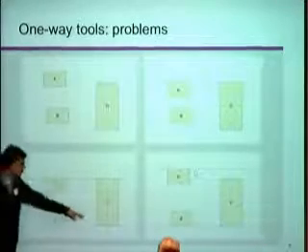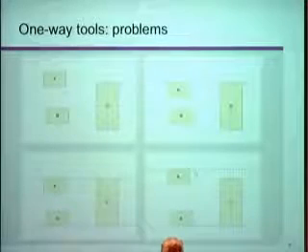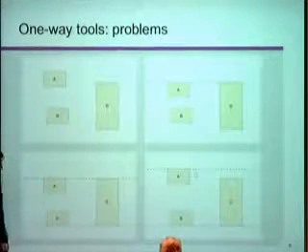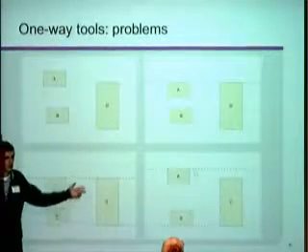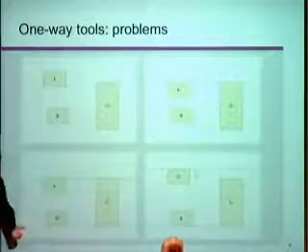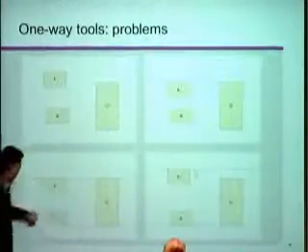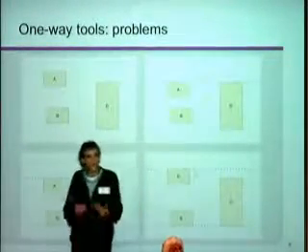Next, they select shape D and they select shape B, and they create an alignment with the bottom of these two shapes. What actually happens at this point is, okay, the Y position of B is constrained to the guideline. The Y position of D is also constrained to the guideline. At this point, it can't be constrained to the Y position of both these guidelines at the same time. All right, so at this point, it's just constrained to the bottom one. And the user will not know this. They can't tell looking at the diagram at this point. It's only when they interact with it that they find out that this is the case. So when they drag this guideline, they find out that the relationship they set up is no longer there.